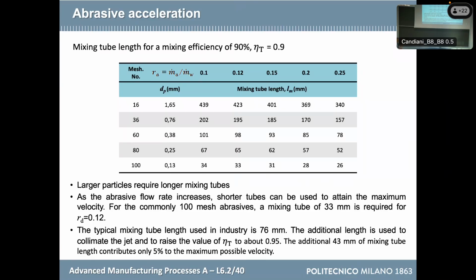But when we use a small bore in the focuser when dealing with a micro water jet, we needed a focuser with a hole of 0.2. Obviously, we couldn't use the usual length. Otherwise, with such a small jet, we would have lost all the power because of friction. In the case of small jets, you have to reduce the length, and we use a 10 millimeter focuser, so it is really small, because the bore was small. Consider also that making a hole in carbides with such a length and such a small diameter is really complex.